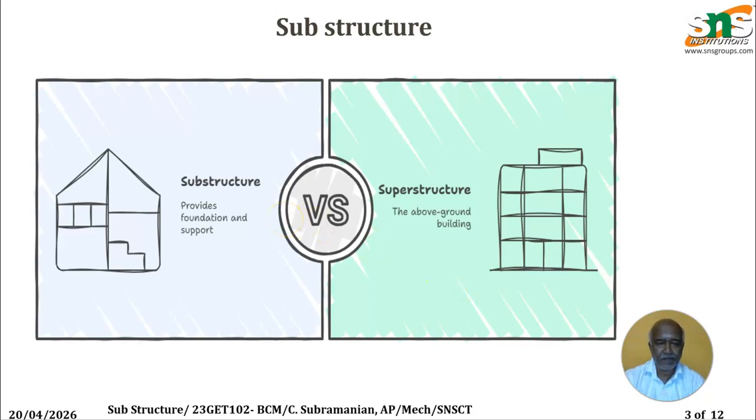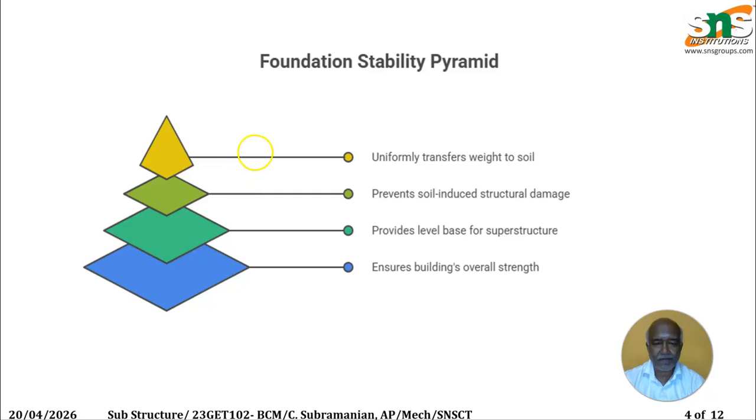Before studying foundation, we must say whether it is a superstructure or substructure. Substructure means at the foundation level, which provides the foundation and support for the structure. Whereas superstructure is above the ground, like a multi-story building. And the stability of the foundation mainly depends upon the soil, the water content, groundwater level, and also the rocks, and what type of building has to be built.